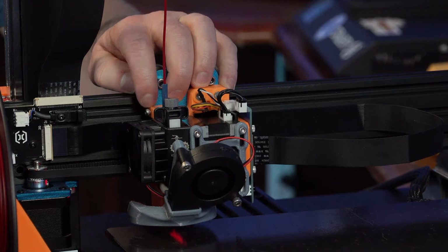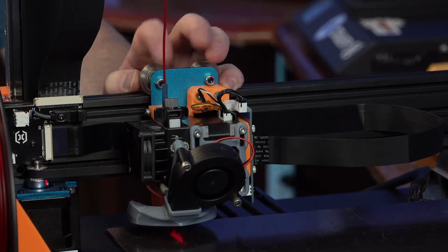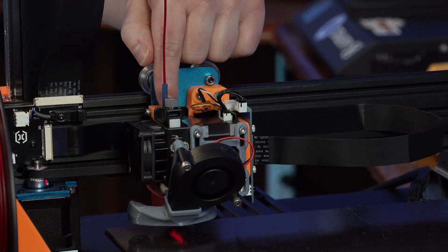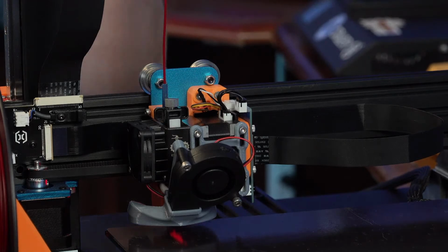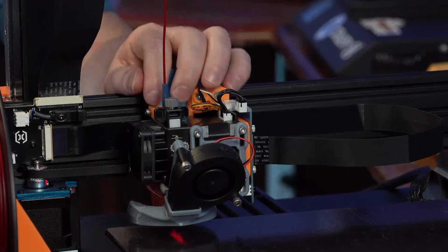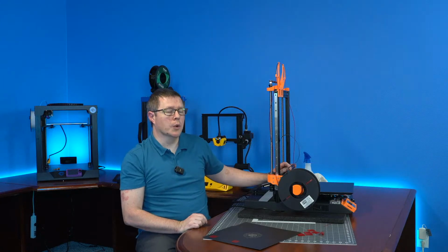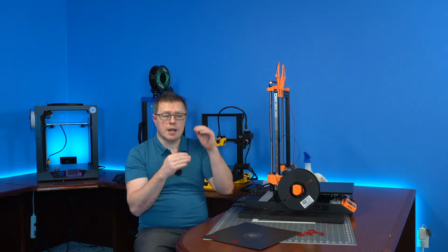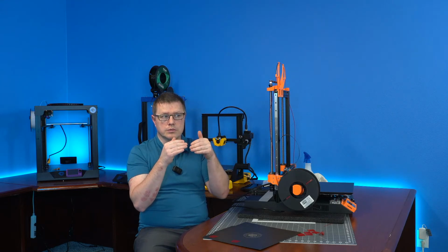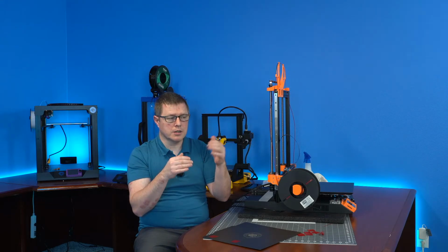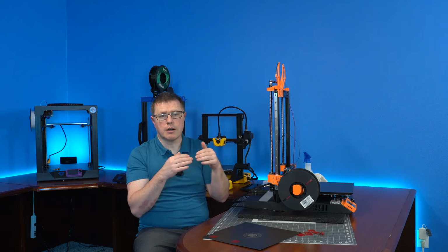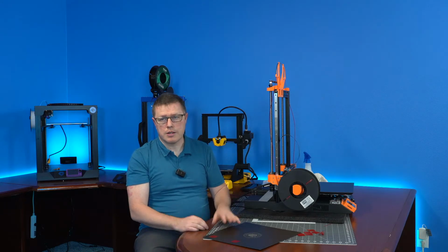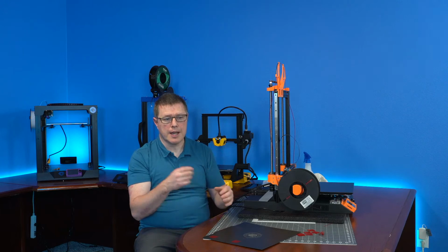Now I do have to at some point, hopefully tonight I'll remember, move that screw hole closer to the gantry just a hair. I've had a few people complain that it's not triggering, because it's not quite centered on the end stop, so I got to move this screw over in the model so it's a little bit more centered. Some people said, use a countersunk screw or something like that that's got a bigger head on it so it triggers.